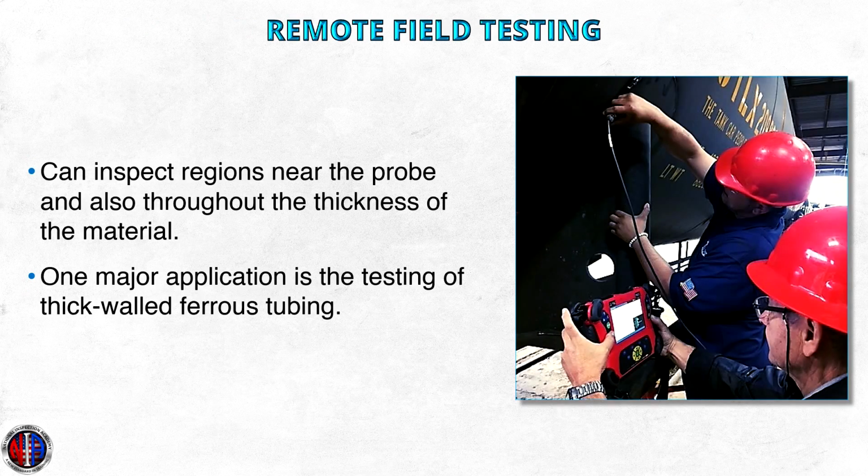Remote field testing. Remote field testing, or RFT, can inspect regions not only near the probe but also throughout the thickness of the material. A major application is the testing of thick-walled ferrous tubing, where RFT shows equal sensitivity to internal and external discontinuities.